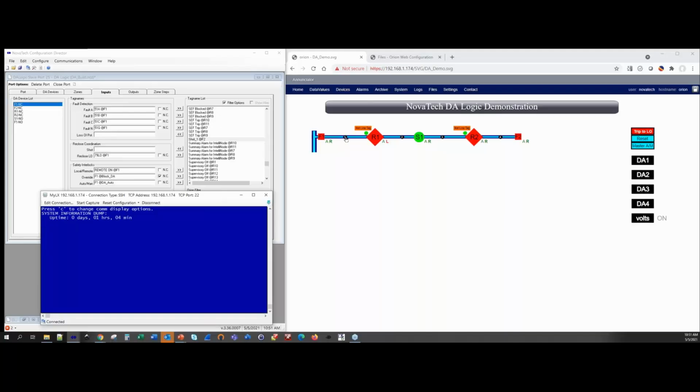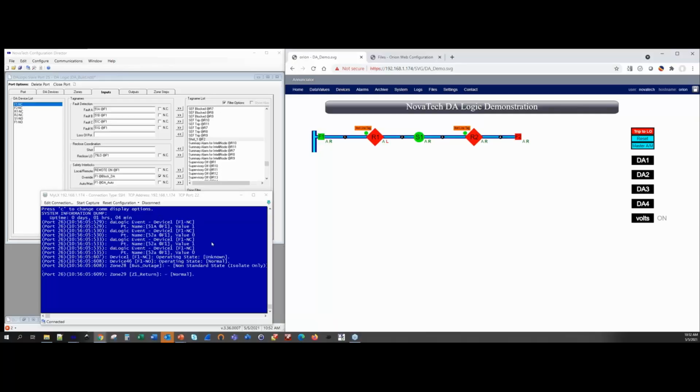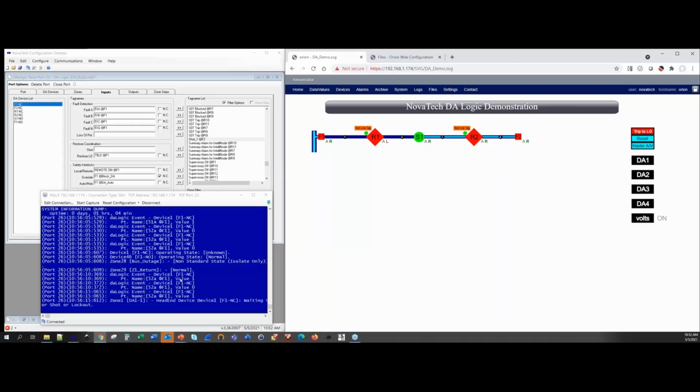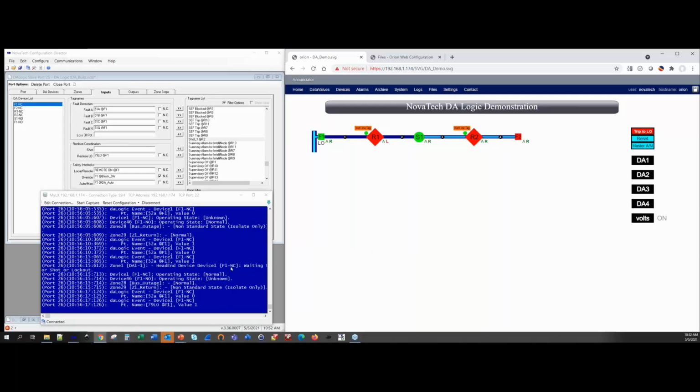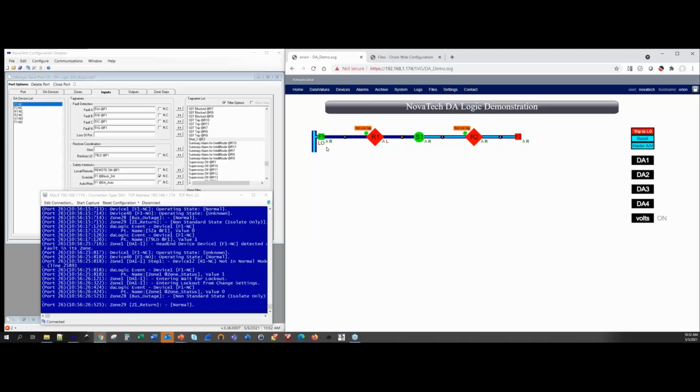And for that same fault that we had on feeder 1, let's initiate that test. And we will see step by step that we have a fault coming on the system. And it will say that it identified a fault in zone 1 in just a minute. Okay, it's going through the reclose, got the lockout, and it says reclose its head-end device at device 1, F1.